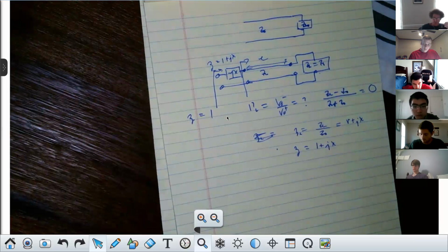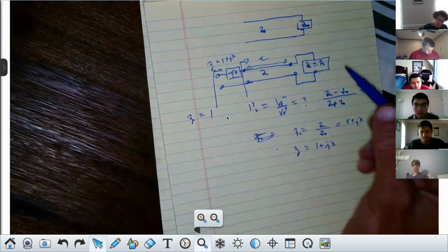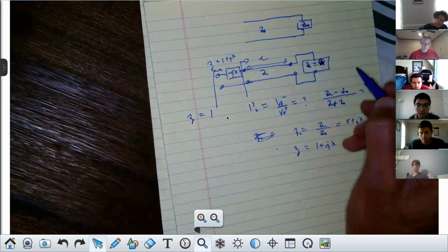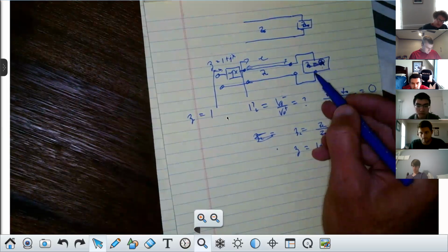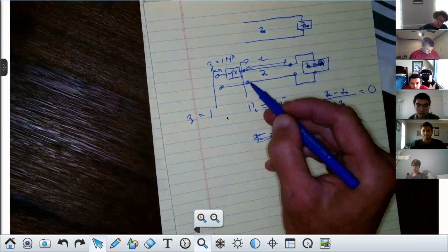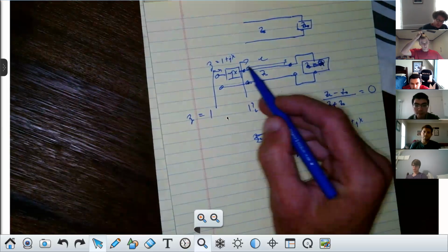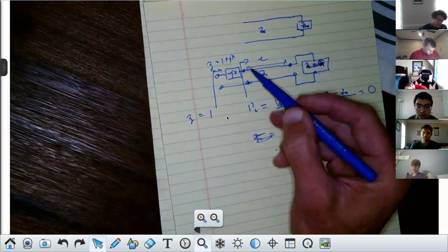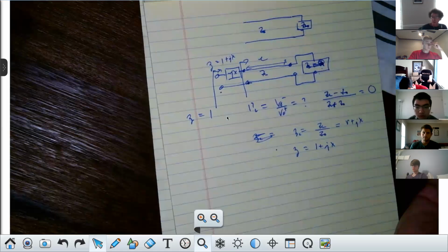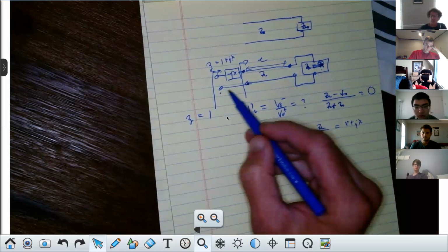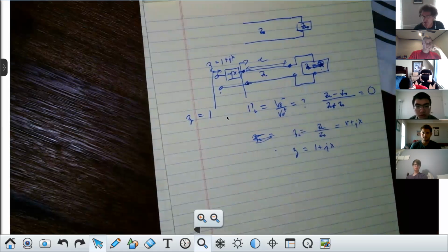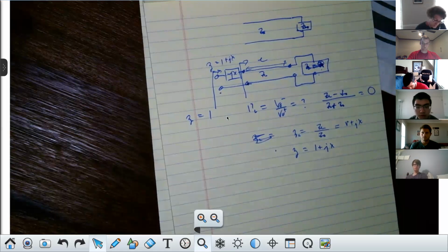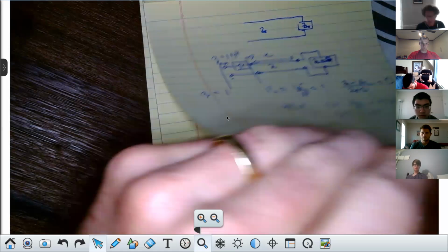I want you to think about what I'm doing. First, I take a load impedance, and forget about Z naught here. I normalize it, and now I'm moving until I hit the point where the normalized impedance will be 1 plus JX. Then I add an impedance that would be minus JX, so the net impedance on the other side of it would be just 1. That's normalized. When I unnormalize it, I have the characteristic impedance going in here equal to Z naught, and the reflection coefficient would be 0. All right, now that's my goal.